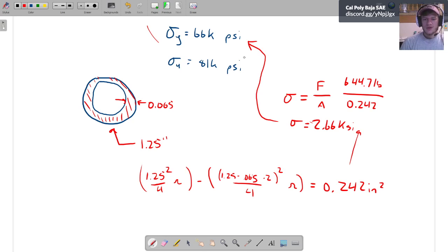So with, I believe, a rollover, the bending in those members is decently high. And in reality, the reason that we use 1.25 inch 0.065 is because that's what it says in the rules that we have to do for the overhead members. But there are plenty of our chassis members that we do actually downsize from the rules, which you're allowed to do if you can prove that they're strong enough to do so.